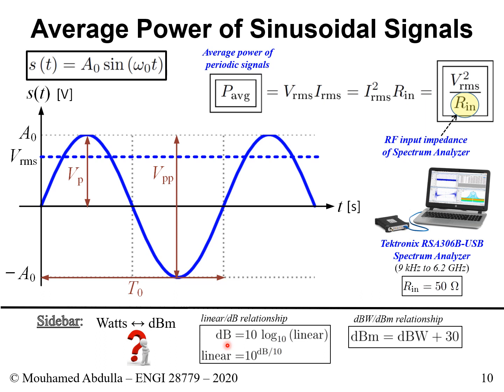If it's a power difference, it would be in dB. If it's a measure of power and the input is in watts, then this would be dBW, dB watt. If the inside is a value in milliwatt, then this would be dBm, which basically stands for dB milliwatt, but for some reason the W is dropped. We just write it as dBm.